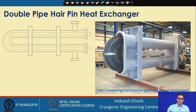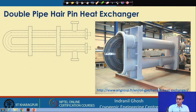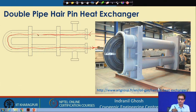So, the double pipe heat exchanger, if you look at it, you can understand the size of the exchanger from this diagram, and you will find that the fluid is coming from one end to the other end through this bunch of tubes. If we look at it schematically, one fluid will be entering from this end, flowing through this inner tube from this end to this end, and coming out from this side. This is one of the fluid streams. The other fluid stream will come from this end.